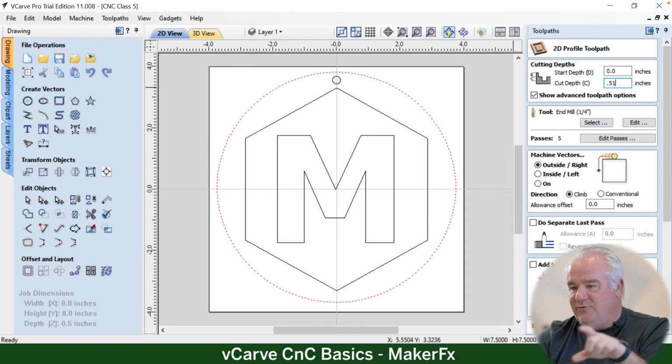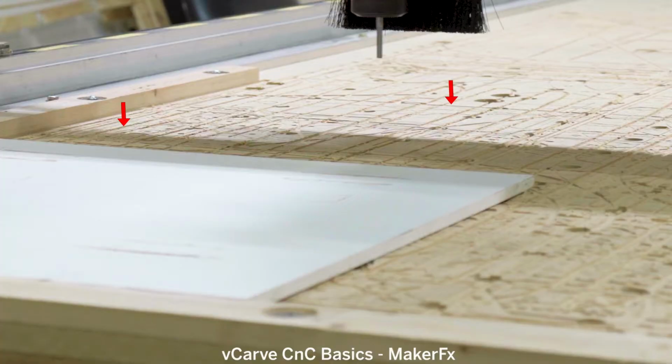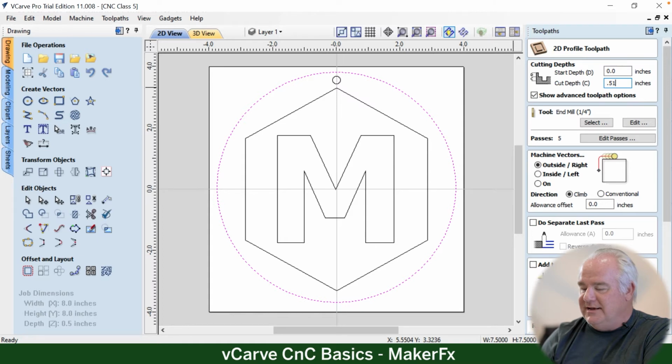If you want to be precise in the material you have, you can measure your material and change it when you set up the job type. That's up to you. But what you're going to see on the machine is we have a spoil board, a piece of plywood or MDF that's there for us to go all the way through and cut through. So this is not necessarily an exercise that has to be in precision.